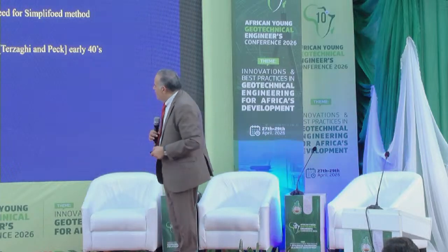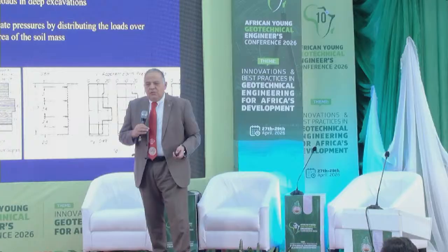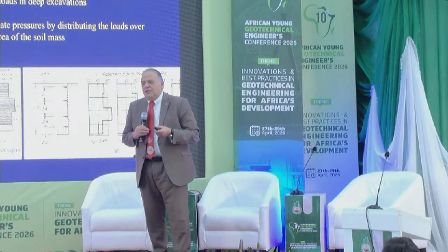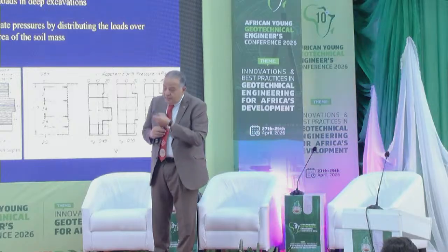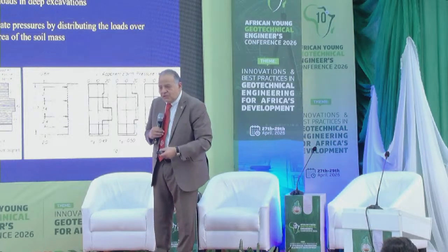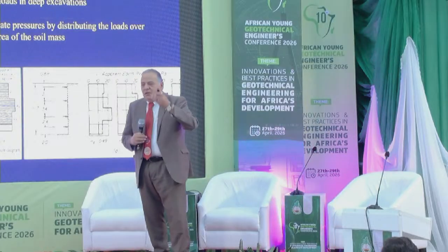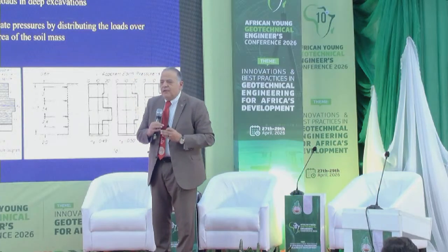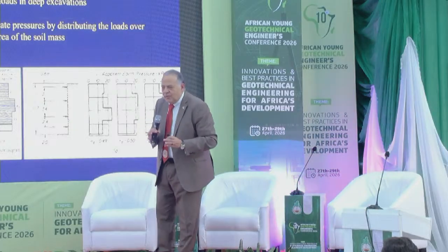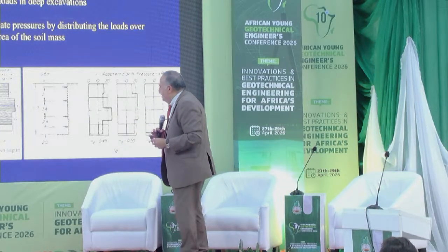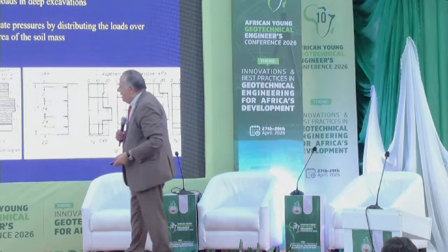earth pressure. In the apparent earth pressure, during any excavation, we observe or measure the forces in the support, in the strut, and then we take this force divided by the area of significant or relevant pressure that is acting on the wall, and then get a distribution of pressures behind the wall.